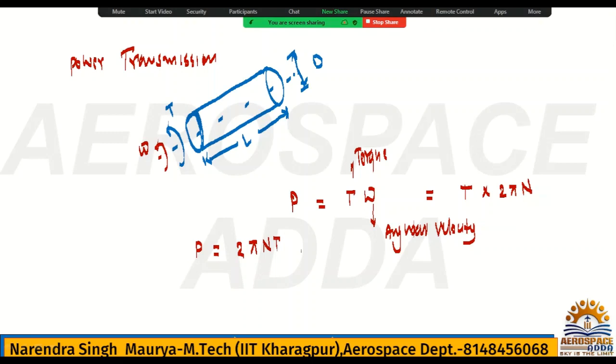Now, if this is the formula, then here this n will be in revolutions per second, RPS. But if you divide it by 60, then this n will be RPM. You know that, okay? So this formula is important. P is equal to 2 pi nT divided by 60.